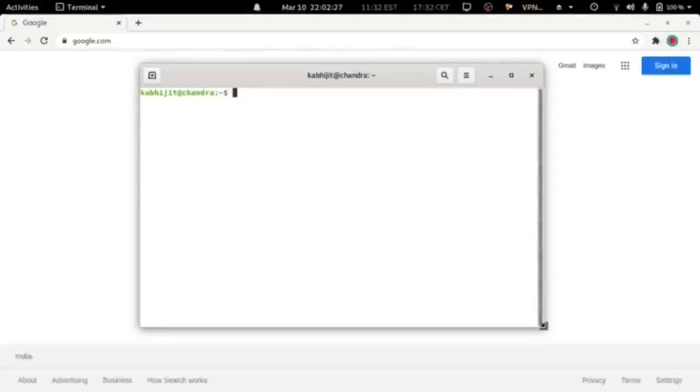Gschem and all the other tools that are under this gEDA family, they all follow the Unix philosophy of being independent tools that work well together. So which means that as tools they are fairly independent. The implementations, how they work, is developed sort of independently, but they adhere to common standards for input and output file formats, for interfaces and things like that, which allows an end user to use all of these tools together, but also allows the end user to use any other tool in place of one of them. For instance, if you don't like gschem as your schematic editor, you should potentially be able to use something else. If you don't like gnetlist as your netlister, you should be able to use something else, and so on.